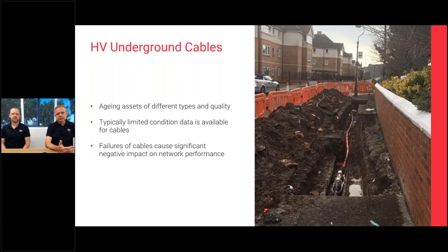Once you install the cable, it's very much a case of fit and forget. The cables are directly buried. There's no visual examination you can do, there's no maintenance and things like that. So how do we know the condition of our network? If we've got an aging network, with cables 40, 50 years old or older, and a large distributed network, how are we going to make an assessment of whether we have a bow wave of failures that are going to come up?